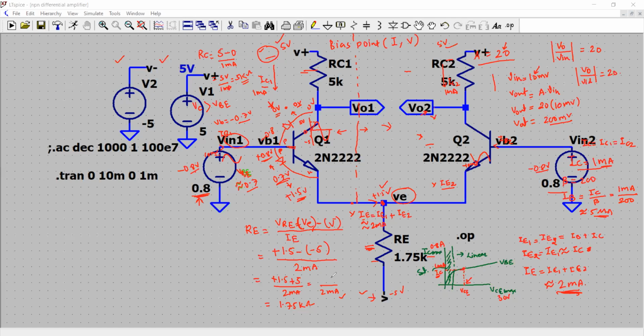So that is your 6.5 volts divided by 2 milliampere, and accordingly the resistor value is going to change. So let's calculate that. So it is 3250. That is 3.25 kilo ohm. Because the voltage got increased, your resistor got increased for a given value of current.